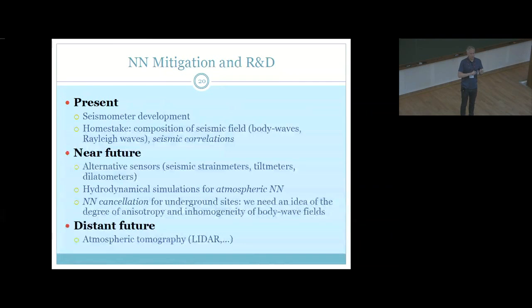But what really worries us is that we don't have a laminar flow of air in the end, but we have surface structure, and that will cause turbulence at specific scales. For example, if you have a building of a specific dimension, you will have characteristic frequencies in your streamlines, in the motion of your air. People try to make some analytic modeling of that, but all I can really think of is some kind of numerical simulation that can handle turbulence to some degree.